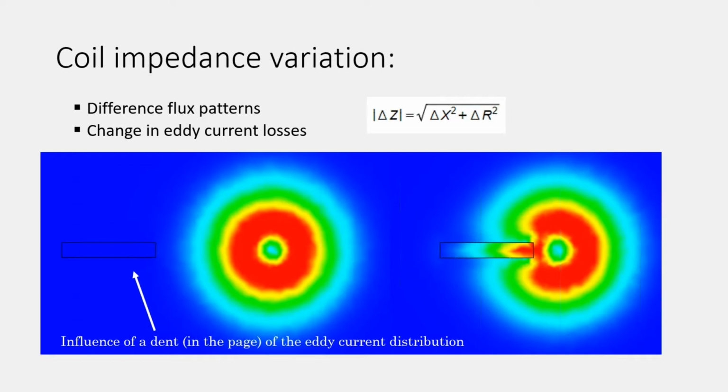So if you manage somehow to catch this change in the coil impedance and to characterize it, you will be able to estimate, for example, the depth of a crack or its position, size, etc. So the role of electromagnetic simulation software like EMS in this problem is to help you reconstruct the impedance profile for a few different probe positions.